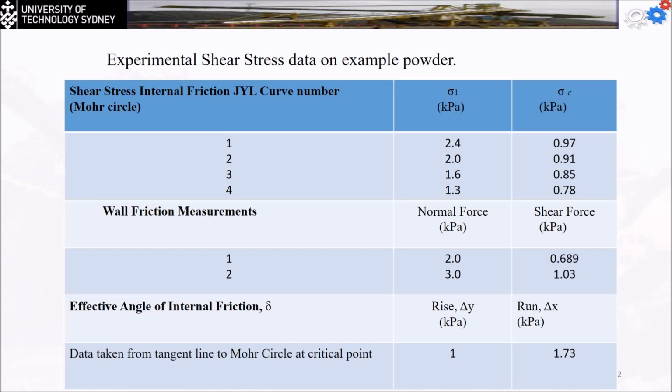And to recall this one, we have 2 layers of the materials. We added the force on the top of it and started to slide it with the horizontal force. So there will be internal friction between the particles of the material itself, and that's what we got. That's the stress I added, and that's the stress resulting to push the things horizontally. Now, simply you have to do that because you cannot measure the friction value directly. That's actually what's happening even if you do the coefficient of friction for the solid parts.